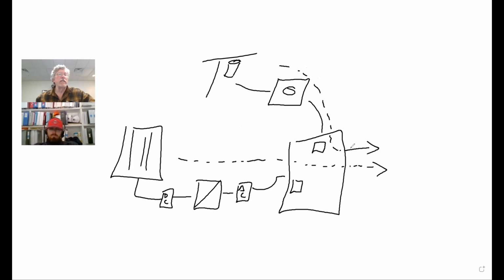And these will be happening simultaneously. So not all of the power is being drawn through the inverter for the loads, only that which is coming from the array. Then what happens if I am generating more power than I need? Well, some of it is going to go to the load, but some of it is going to go back out onto the grid. So the grid becomes a load.